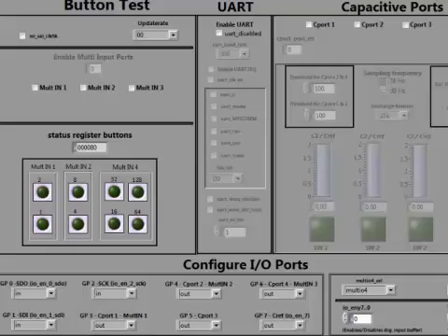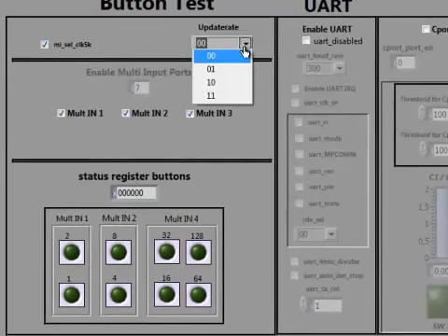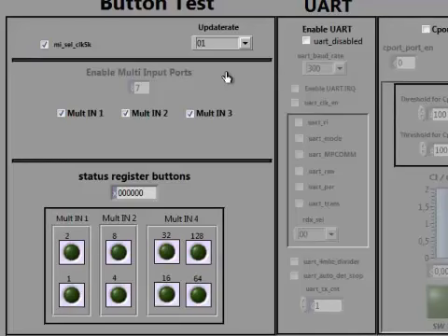To configure a multi-input pin, first enable the multi-input pin, then configure the pin as input, next ensure that the digital input buffer on that pin is switched off. Select the scanning frequency for the keys by selecting these 2 options accordingly. Now the key is ready to use.